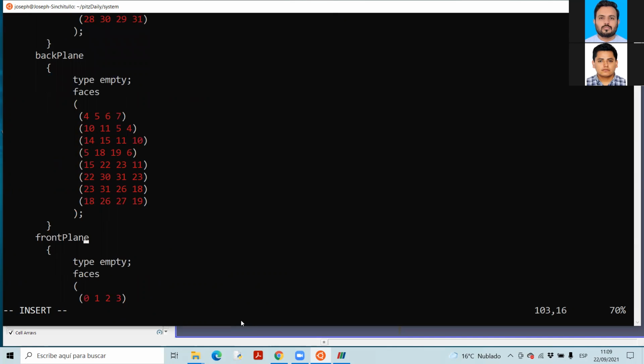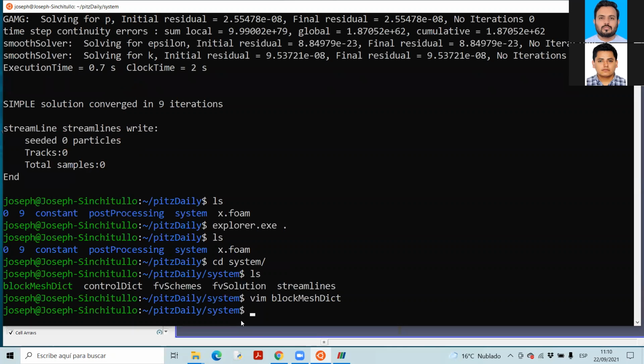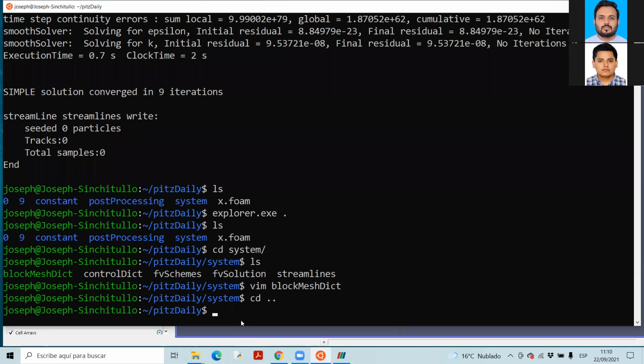Yeah, I have got it. Escape it. Press escape. Yes, good. cd dot dot, enter. Right here, blockMesh. Enter.